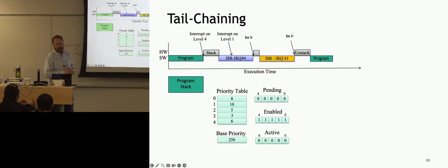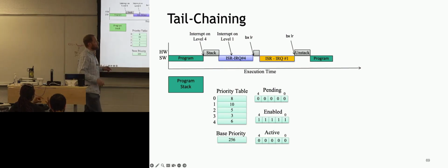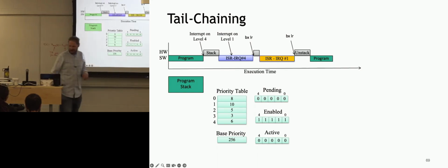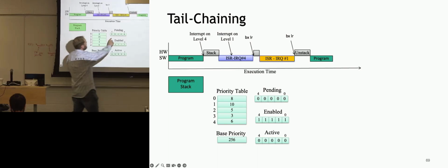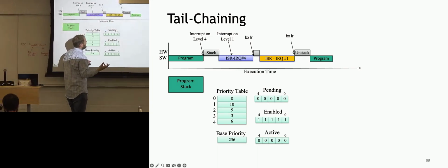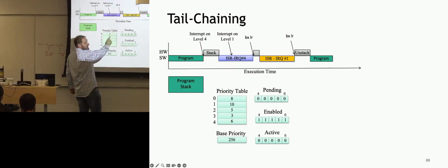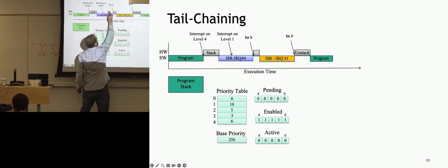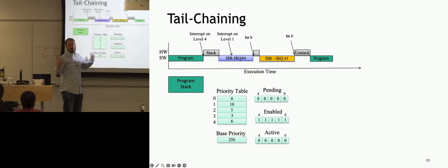What is the same preemptive priority compared to, let's just say, a lower sub priority? So I think we have an example of that next. No, we have late arrivals next. So the question is, this was a lower priority, so it waited here. When does sub priority come in? Imagine if I had a number of interrupts that came in all at level 10. So now maybe 1, 2, 3, 4 interrupts are all pending. We see them pending, and they're all level 10. How do you determine which one of those goes first?